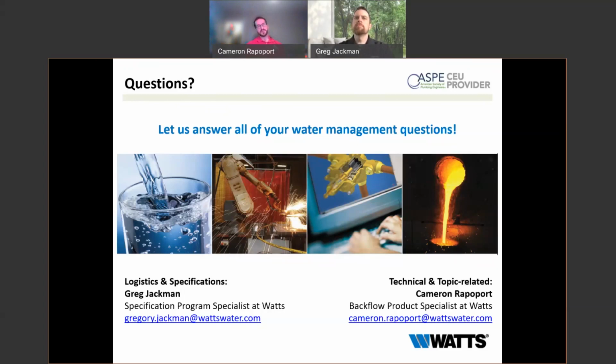Yeah, but only if you open them. It's a good question. It represents a potential cross connection, but those valves are normally closed, right? So you have to go in and open that valve, which you would either have to do underwater, right, you have to drain that pit before you test it anyway, or you'd have to leave it open, and you would notice because water would be shooting out of it. So it's a good question, and an interesting consideration.